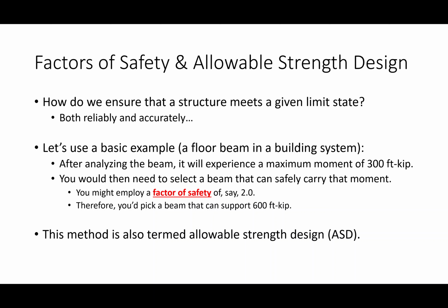Okay? Now, that is a design philosophy. A design philosophy is basically a strategy to meet a limit state. So here's the limit state, here's the condition that we need to meet. And a design philosophy is basically saying, how are we going to meet that and account for the big word, which is uncertainties, okay? That's what a design philosophy is intended to do. And a factor of safety does handle that pretty easily. Just take the loads, double them, boom. There's your uncertainties. You don't have to worry about uncertainties because we just did that, okay?